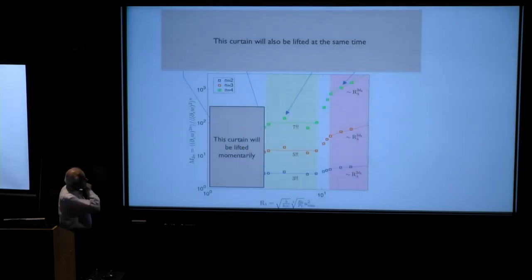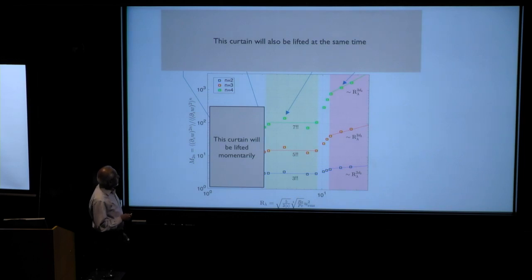And this is the result for the convection flow. As a function of this Reynolds number, these moments are plotted here for n equals 2, 3, 4. You can see in this range, they are pretty nearly double factorial corresponding to the Gaussian state. And in this narrow range of Reynolds number it takes off again. These are not arbitrary powers, but powers that are characteristic of fully turbulent flow. It'd be nice to have more data here, and it will be generated in due course.